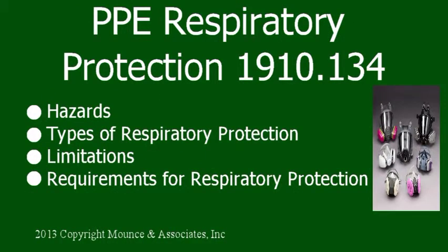PPE respiratory protection. Respiratory protection protects your lungs and health from various types of air contaminants. Before you begin wearing your respiratory protection, you must be fit tested. Fit testing is required, and it goes through a series of steps to ensure that the PPE you are wearing fits your face and you are able to breathe and move comfortably. No facial hair should be in the way of the protection as it affects the mask you are wearing.